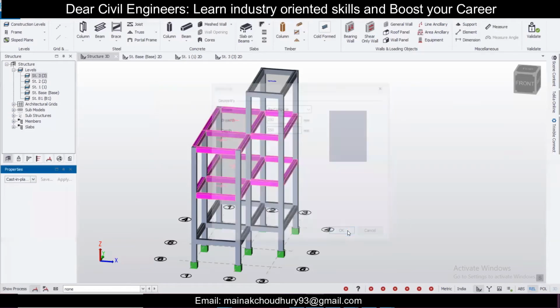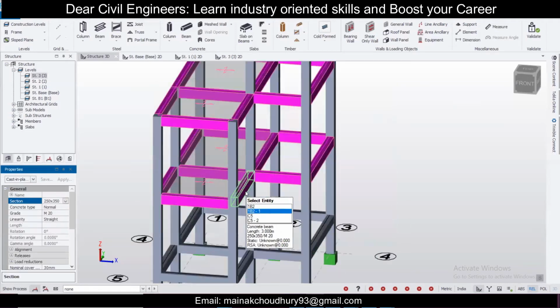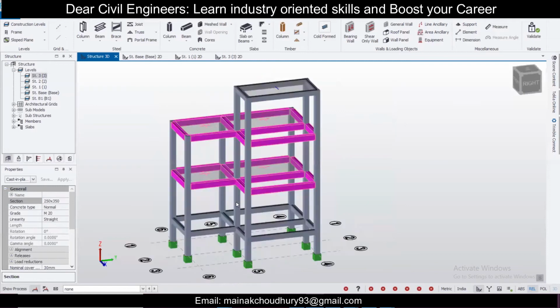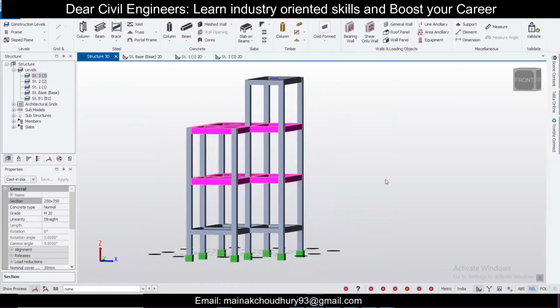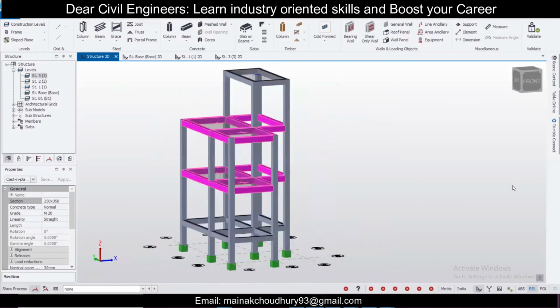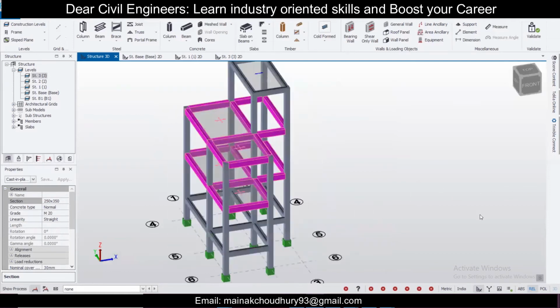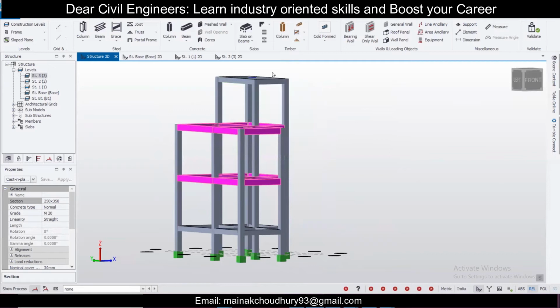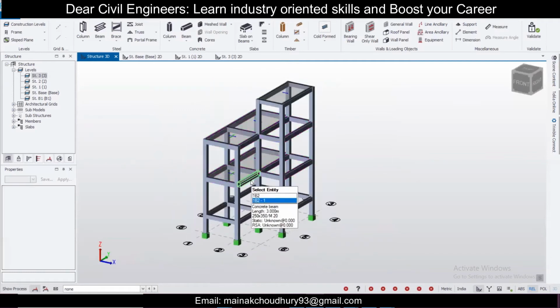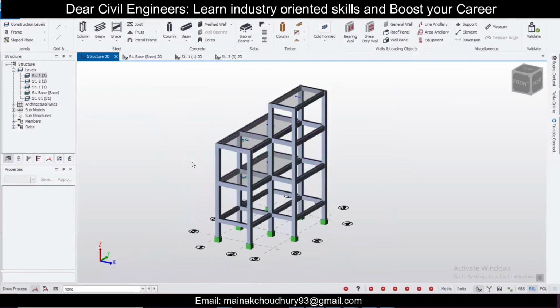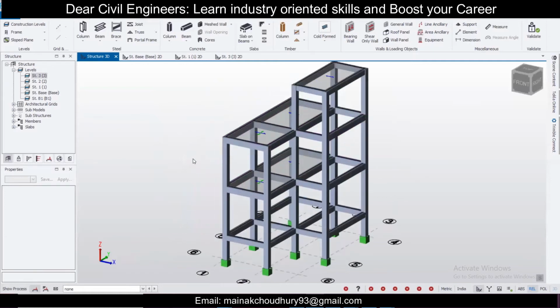The depth we have increased a little bit because the roof beam might not pass with 300. Let's give a higher thickness. So we have provided 350 mm thickness to the particular beam here, and in the headroom part also, if you need, we'll provide. Now let's go with this, and this is done. So the modeling is now complete for this particular building.